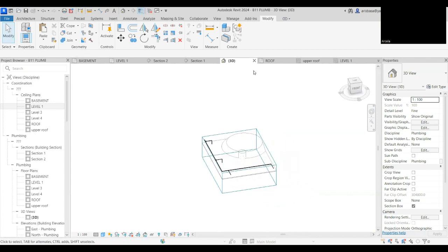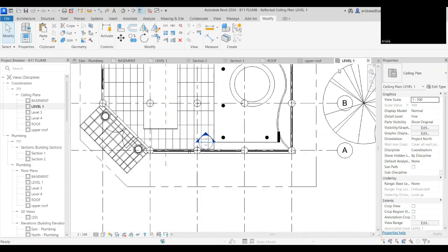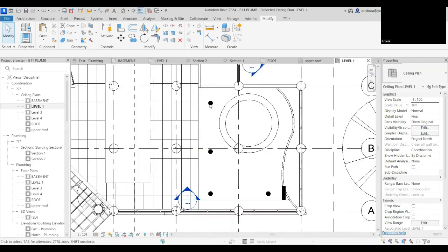Now we can bring in the plumbing model, architecture, and structure, right? Then we can know the flashings. Yes, that's what it's supposed to be. Because when I show you the ceiling, we know that there are sprinklers, so we don't need to put lights there. Otherwise, there's a problem. And above the ceiling, you know that there are pipes, so you want to avoid that if you will have electrical cables, cable trays.